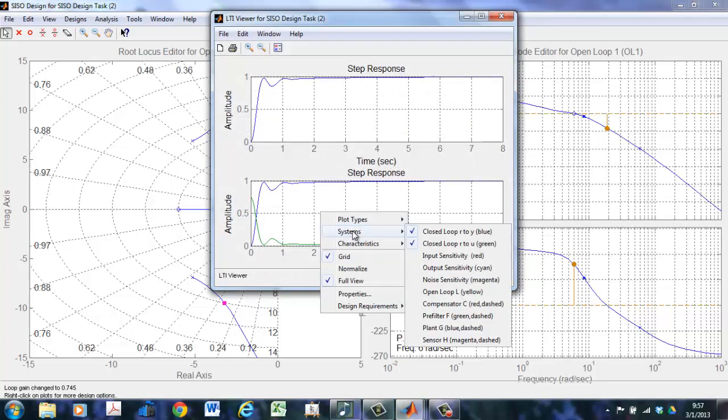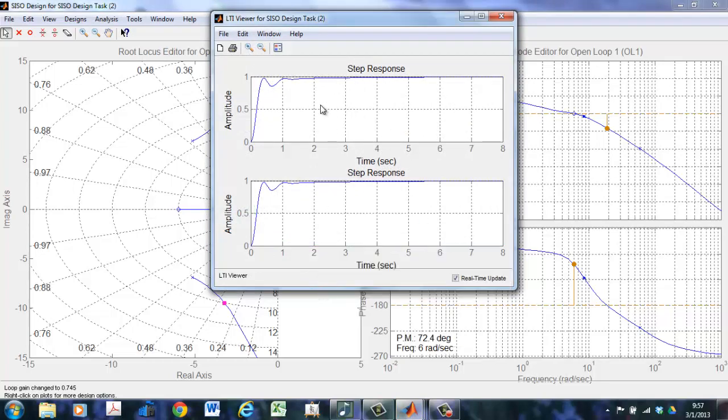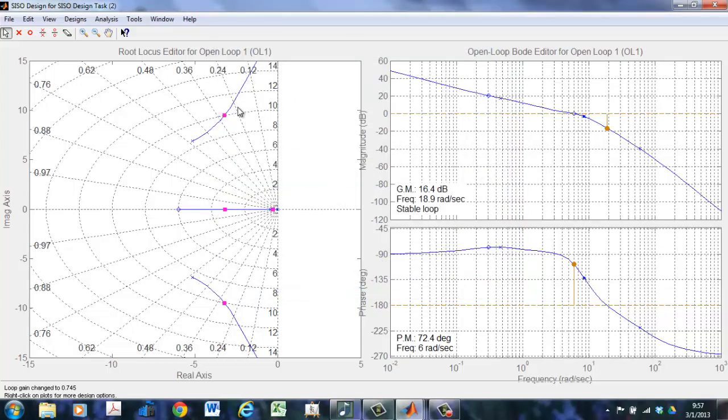And it looks like, yeah, if I could take that little blip of overshoot, the steady state output is good, equals the input. I've got a little oscillation here, and that oscillation I'm almost certain is caused by this pole with damping of 0.3 or so. But I've got good phase margin, and that's good protection against phase loss and unmodeled dynamics.